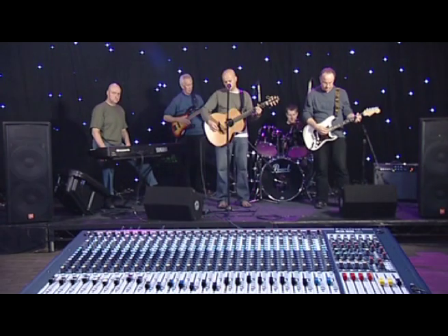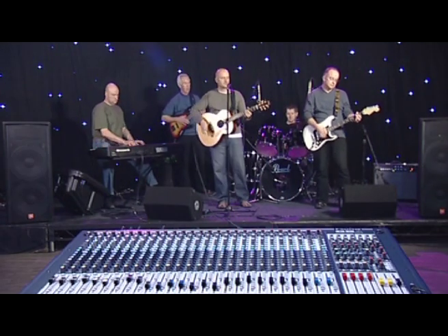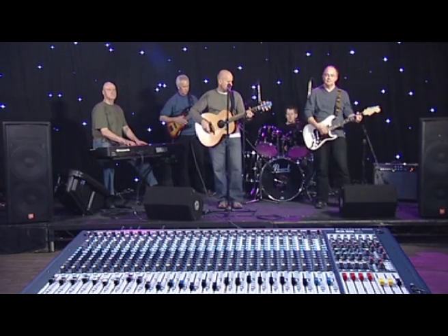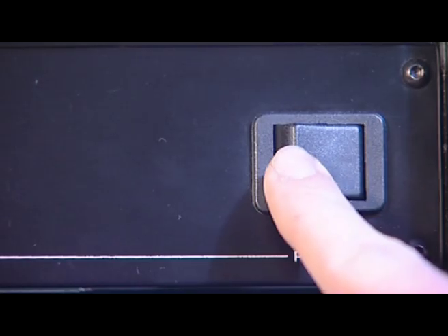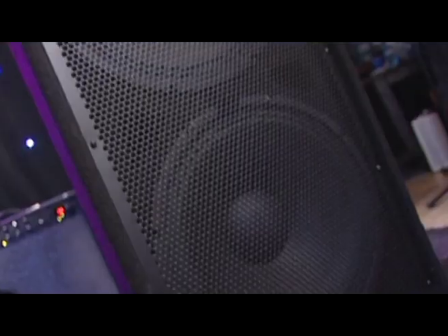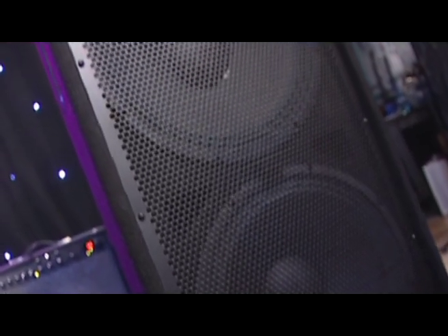Try to put the mixing desk in a position where you'll be hearing the music from where the audience does. When you've set up, switch the power amps on last to protect the loudspeakers from any loud thumps and buzzes as instruments are plugged in.